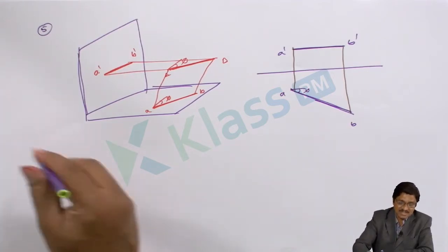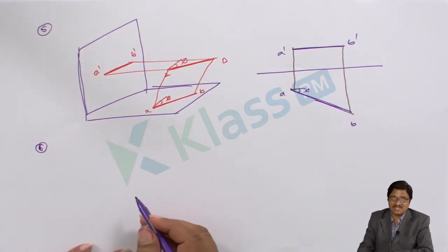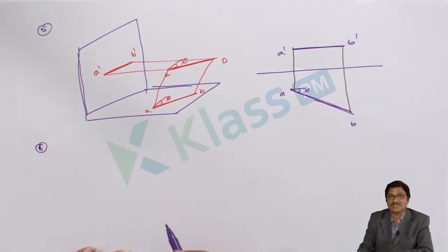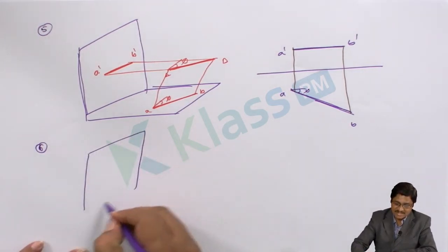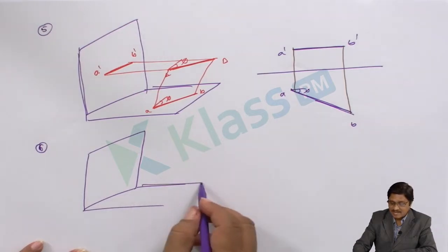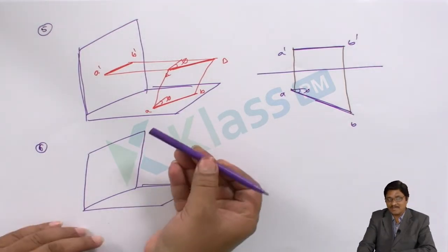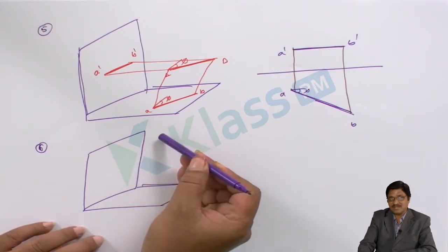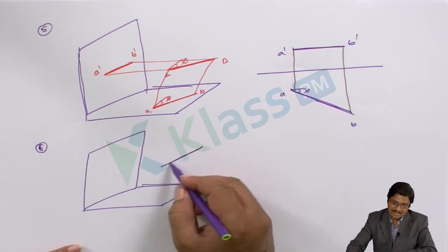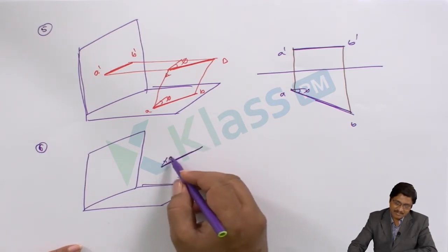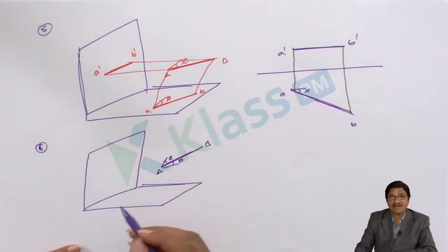After that, the sixth and the last is a very complex position. We cannot draw that much easily. Based on assumption, you have to proceed for that solution. What that means? Whenever they give the plane of references, the line is making inclined with both the planes. That means if the line is like this one, it is making VP inclination as well as HP inclination, a little complex position. So it is making phi and also theta. In this problem, we cannot directly draw.